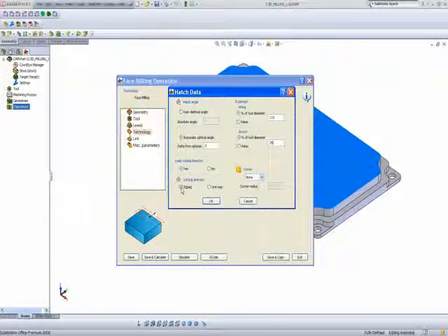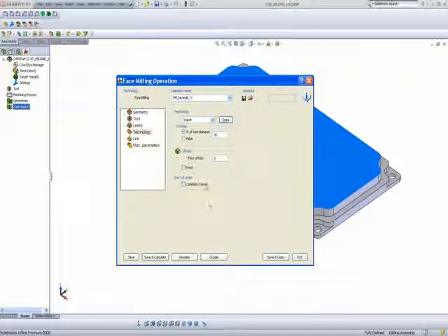Now I can go either zigzag, back and forth, or in one direction. We'll choose the option of zigzag, and my corners, I can have them fillet also. This is particularly good, especially when you're working with higher feeds. I'll say OK. And in the overlap area, this decides what's the overlap between each tool pass. We can leave it at 30% of the tool of overlap, or if I want, I can even make it a smaller overlap, say 5% of the tool.